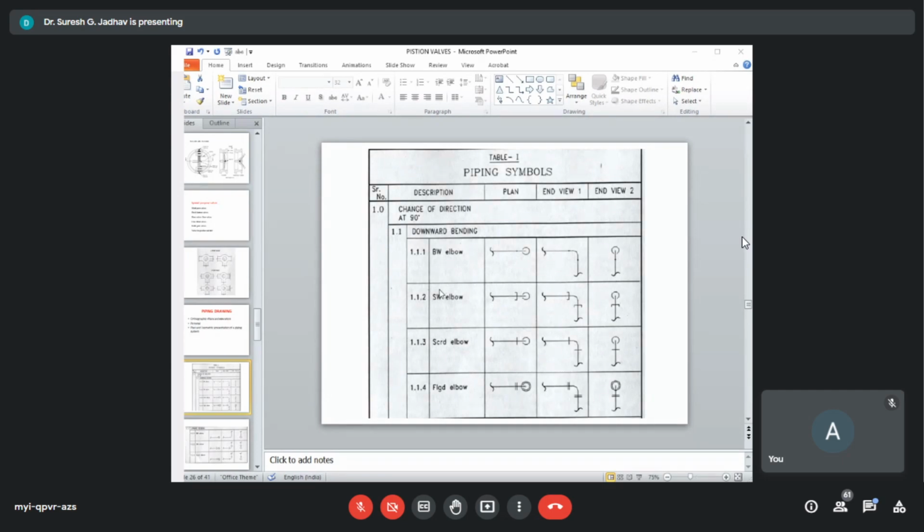The drawing sheet is divided along the length and breadth in equal spaces. The longitudinal blocks are identified by alphabets and those along the breadth numerically. These coordinates are used to locate the area on the drawings. The direction of the north is taken either towards right or left.